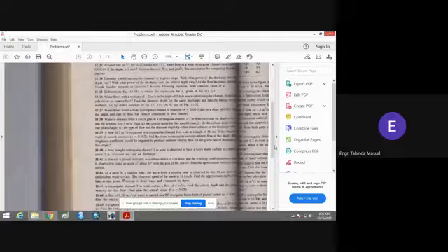Depth of the flow is given, velocity of the flow is given, and it is also given that this is a wide rectangular channel. We know that a wide rectangular channel is one where the depth of the flow is very, very small as compared to the width of the flow. We have to find the state of the flow, whether it is subcritical or supercritical.